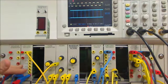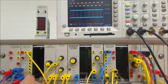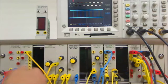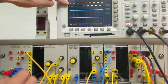For your convenience, I've already wired up the signal according to the block diagram in figure 5. We'll now look at some of the signals and make various adjustments and discuss them as we go. Starting with the sequence generator, which is clocked from the line code encoder output. The line code encoder is clocked at 8 kHz from the master signals, and 2 kHz is output to the sequence generator, which acts as the bit rate for the system, 2 kilobits per second. On screen we can see we have the bit clock, 2 kilobits per second,